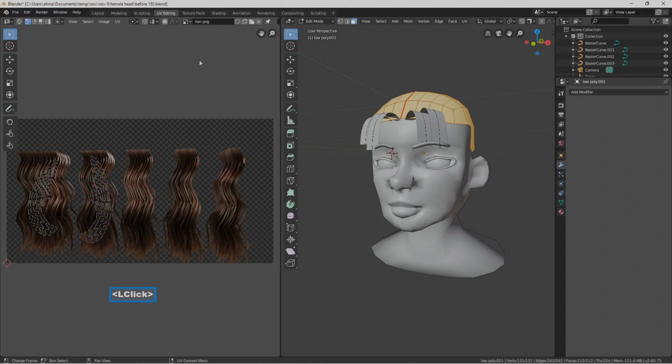I'll left click nothingness, deselect. I'll press O. We could also just click there to turn on proportional editing. I'll left click here, press G. Left click on nothingness to deselect. Okay, what we'll do now is we'll left click to deselect.